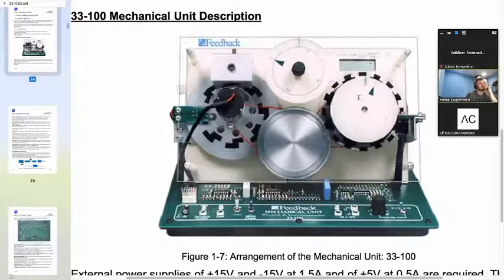Yeah, so that disc is a potentiometer, actually. Mm-hmm. So you see this arrow on the disc that has a thin line? Yes. That arrow is the position of the motor, and you see this blue arrow painted on the top. So that's the reference. If this arrow points all the way up, or it matches this line, that means the voltage coming out of this is 0 volts, which means the position is at 0 degrees.